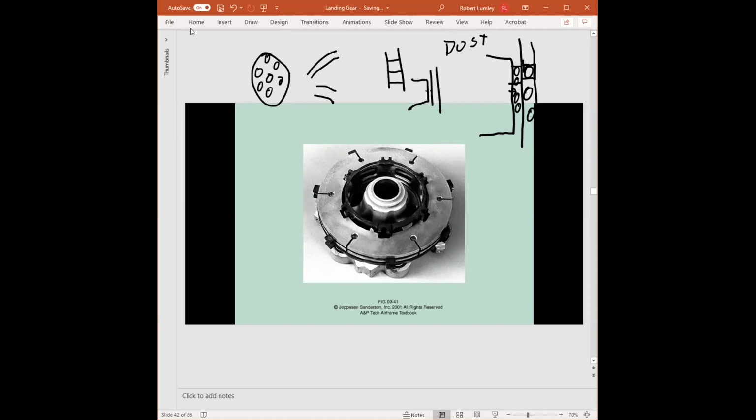I don't know if anybody's driven their vehicle really, really hard before. And when I say really hard, meaning operated the brakes really, really hard for a while, you'll get what's called a fading brake. The pedal feels hard, but you know that you're not getting the proper stopping power. Originally, when you first start driving, you hit the brakes and you're stopping.